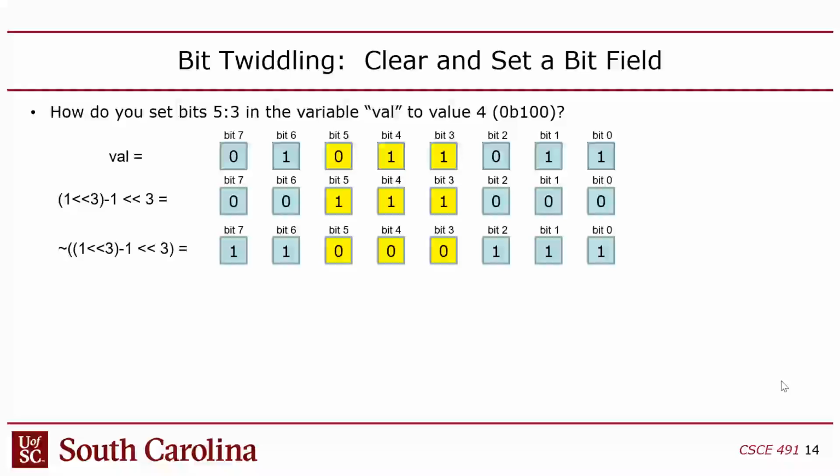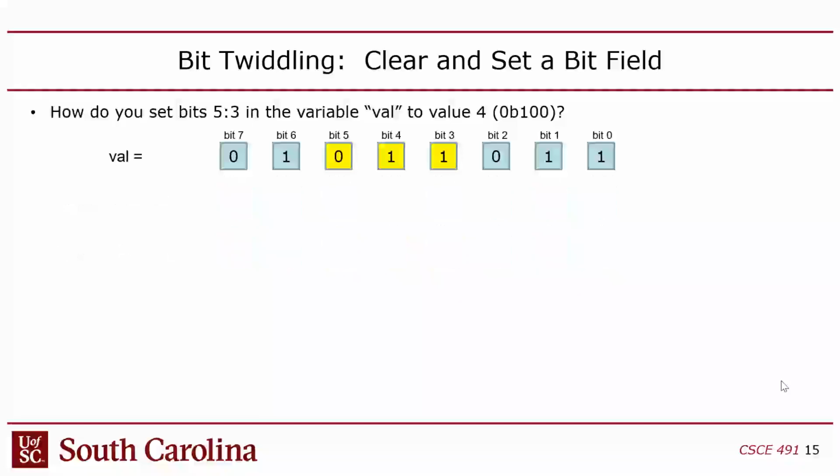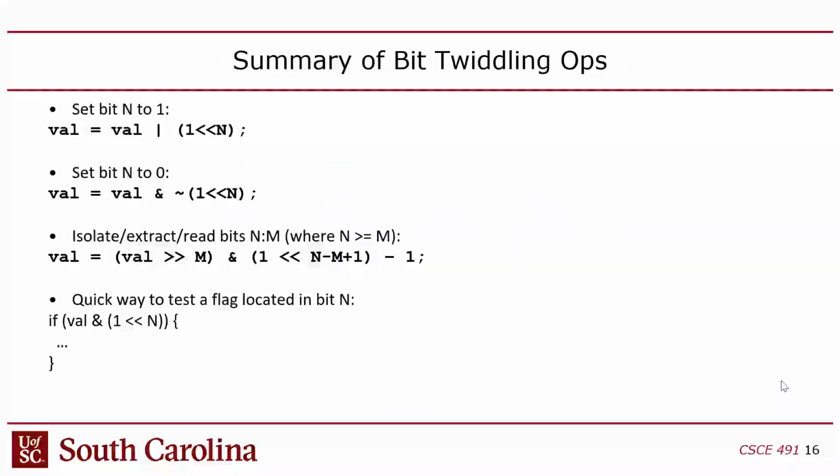Another way to do it is you can write the control register and then read it back and confirm that what you wrote went through correctly, right? But you have to be very careful. I just want to caution you that this always bites me. Be very careful when you start combining these things into complex expressions, because it's not obvious what the order of operations is here. Now, as it turns out, you can look it up.